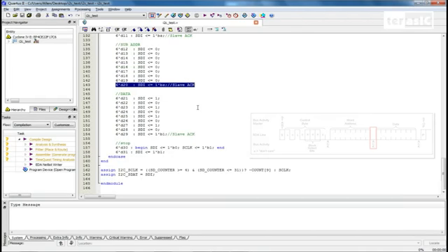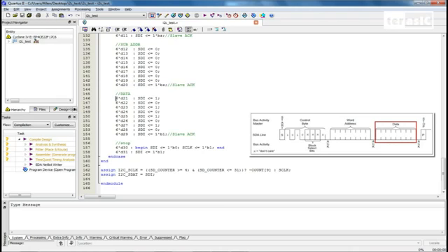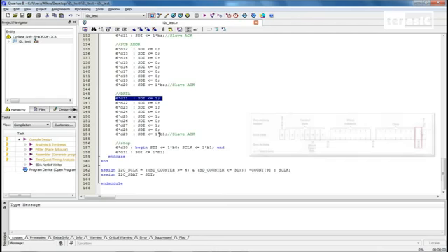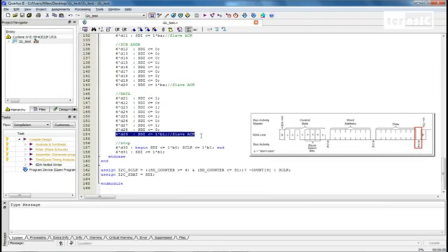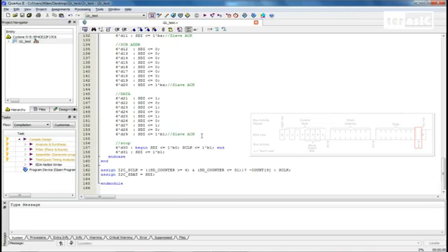After the slave acknowledges, we'll write our data into our register 0. So it'll be AA, which is 10101010, and we'll wait for our slave to acknowledge. So that is the end of our operation. And what we have to do is we have to specify a stop condition.